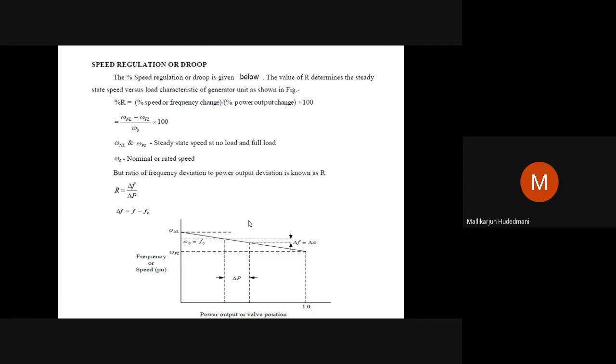Hence, droops are always spoken of with the generator. That is the history connected to why the droop only. Droop of a real generator we will see in the next module, surely. But basically, let us understand why this kind of expectation is there. It is because on a fall of RPM or frequency, that error is fed into the controller to try to open the valve. That's what we are saying.